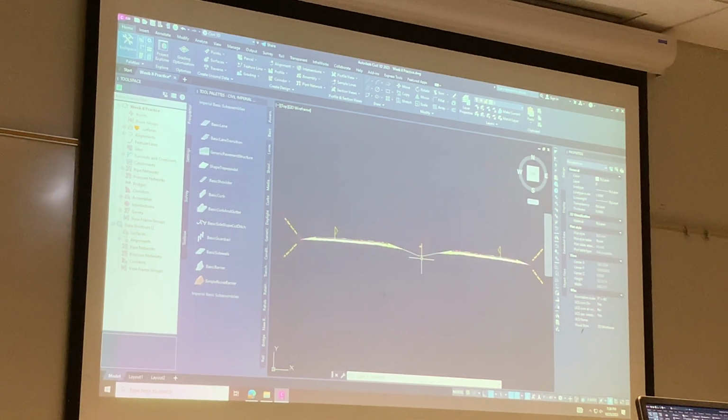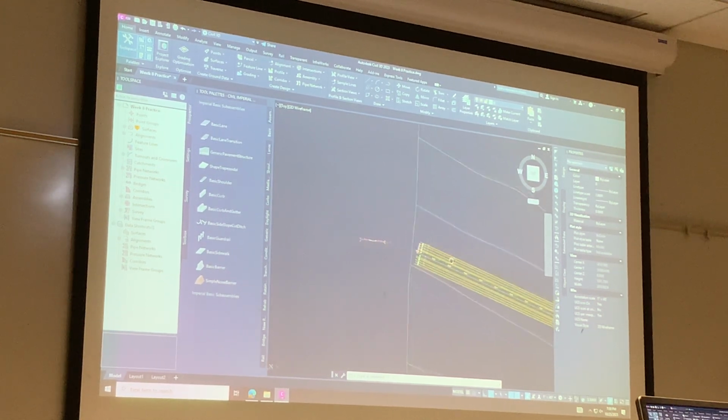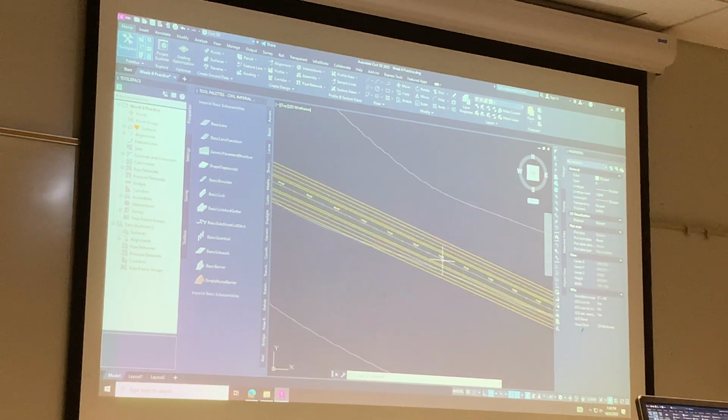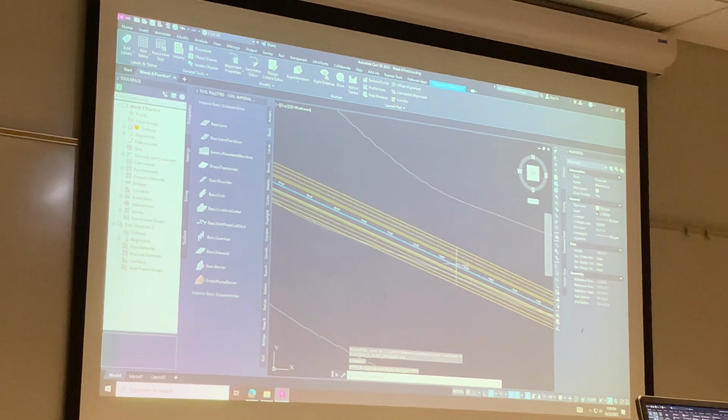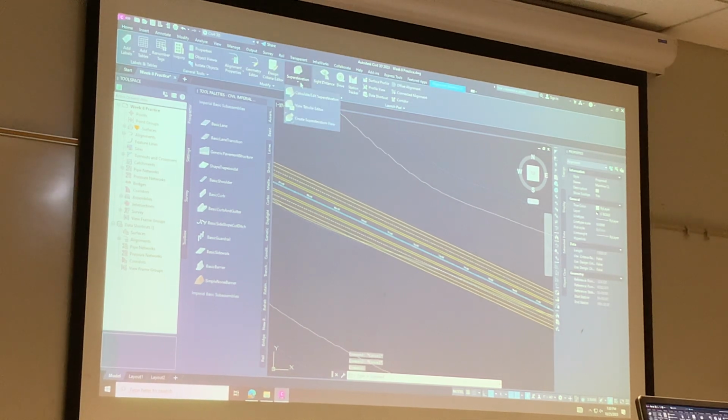No, that's stupid. Don't do that. Do we select the line? You want to make a corridor out of it now? There's one step before that, and what we did, yep, we selected the alignment in the center line of the highway, and we gave it super elevation. So we select that alignment, super elevation, calculate / edit super elevation.